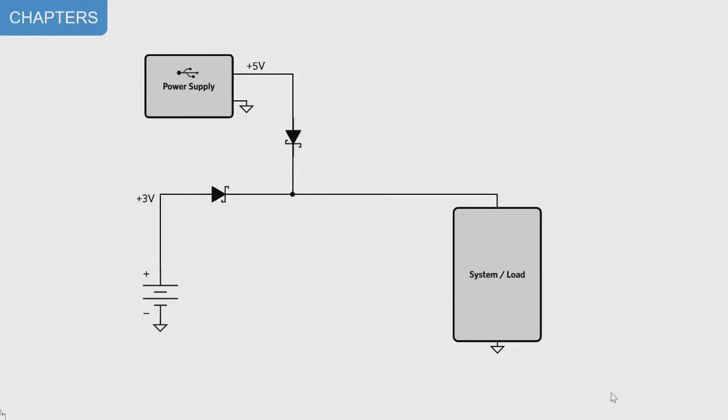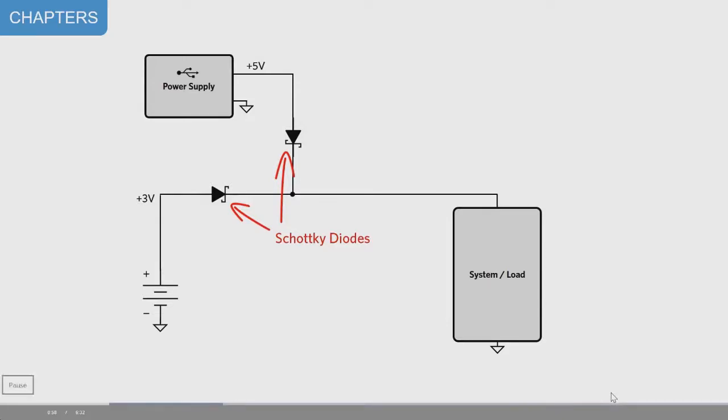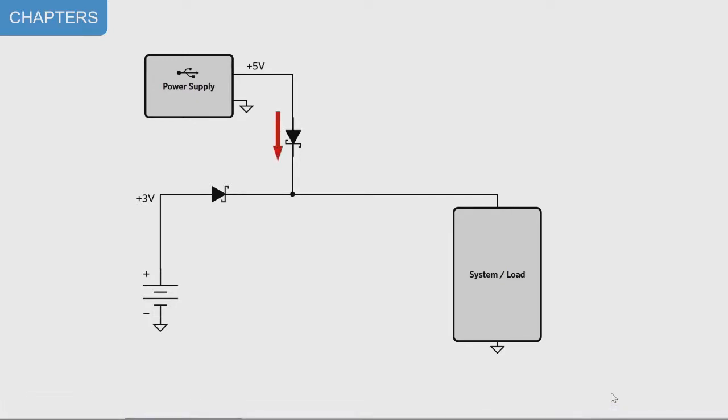The classic approach to switching between power sources is to use Schottky diodes, as they are simple two-terminal devices and have a low forward voltage to reduce power loss. When the outputs of two Schottky diodes are tied together, the one with the higher voltage applied conducts, which reverse biases the other diode. However, using Schottky diodes poses two problems.